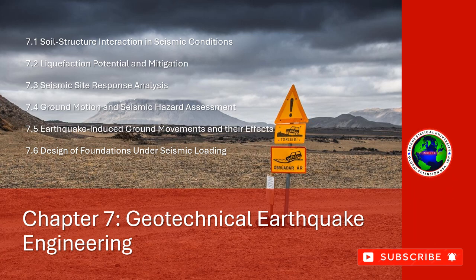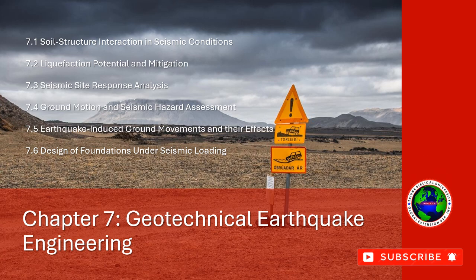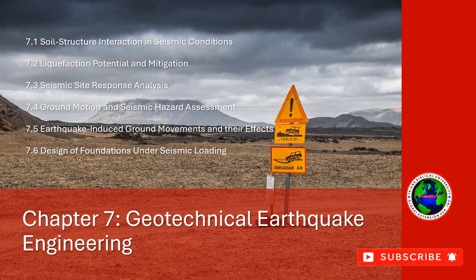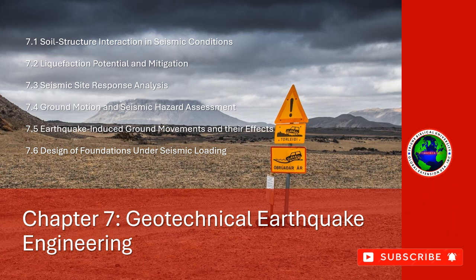Chapter 7. Geotechnical Earthquake Engineering. 7.2 Liquefaction Potential and Mitigation. Liquefaction is a phenomenon where saturated, loose, fine-grained soils lose their strength and behave like a liquid during an earthquake. This sudden loss of strength can lead to severe consequences such as foundation settlement, tilting, and even the collapse of